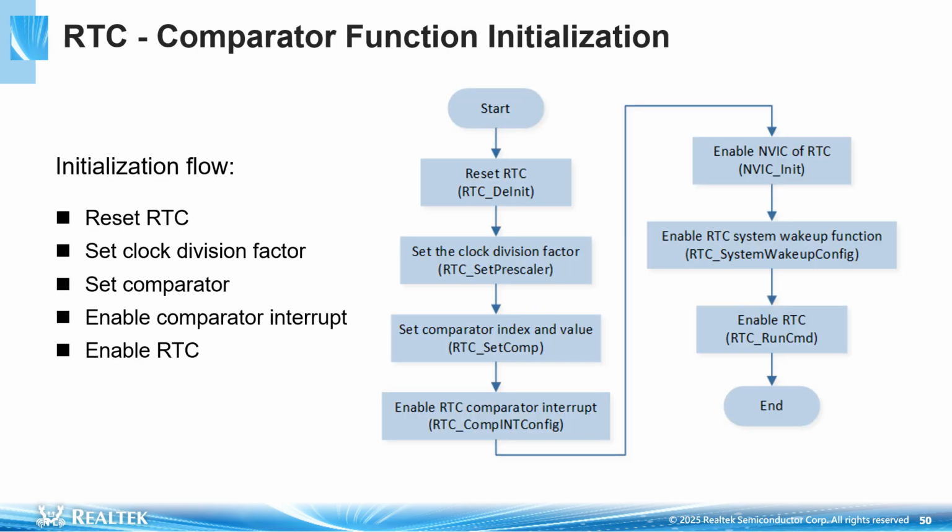The initialization process of RTC comparator function is shown in the figure. Firstly, reset the RTC, set the clock division factor of the RTC, set the comparator value of the RTC, then enable the RTC comparator interrupt, and finally enable the RTC.